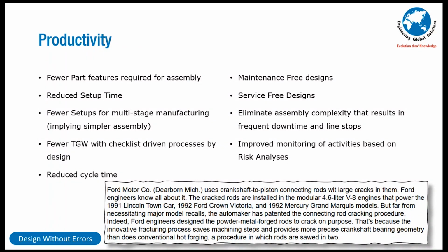Ford Motor Company, you know the big end of a connecting rod, right? Small end of the connecting rod, big end of the connecting rod that gets split in half, then you will put it together. When I was at Ford, during that period, they patented this in '91, '92. I was there till '93. The engine division patented this. What they did, they took the unit and they broke the big end.